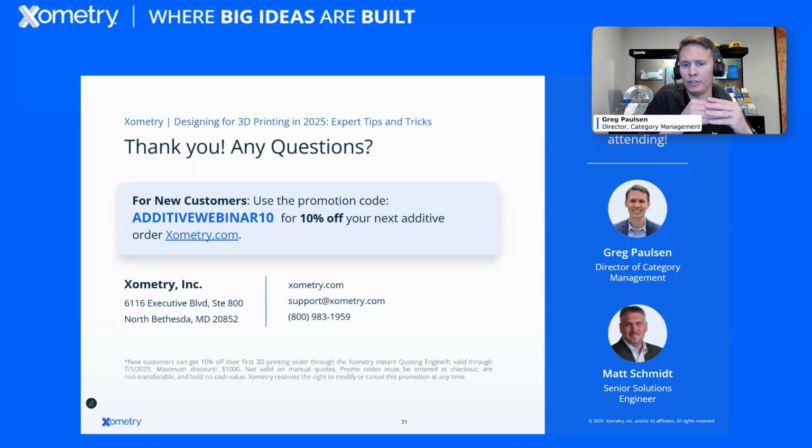Do not design flush to flush. Don't design flush to flush in regular manufacturing either. But there are ways to do that, though sometimes it does require a prototype of your prototype. Something really cool that you could do is slice your file and just print that feature and see how that feature works. So you don't need to pay for the full print if you're just testing a small piece of that feature, and that's very easy to do with additive.